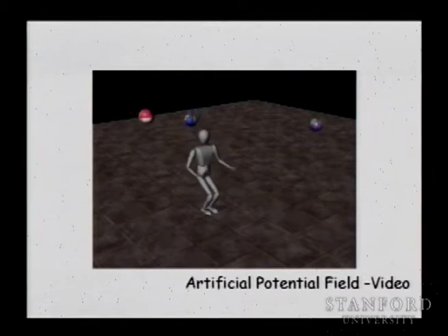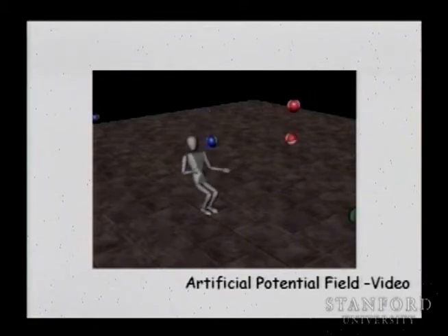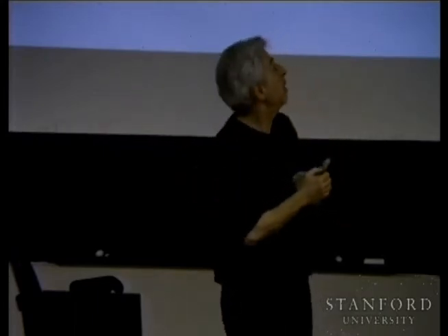And in this video, you can see how a complex robotic system is reacting to obstacles that are coming at it. It's moving away from those obstacles. And this is simply done by using the same type of concept that I described for moving to a goal position. I said we can create an attractive potential energy. In here, to create this motion, we are creating a repulsive potential energy. So if you put two magnets north-north, they will repel. And this is exactly what is happening. We are creating artificially those forces and making the robot move away.